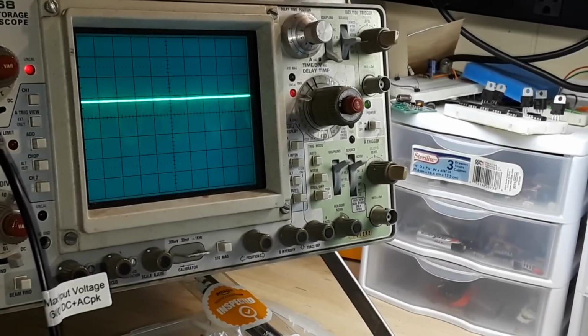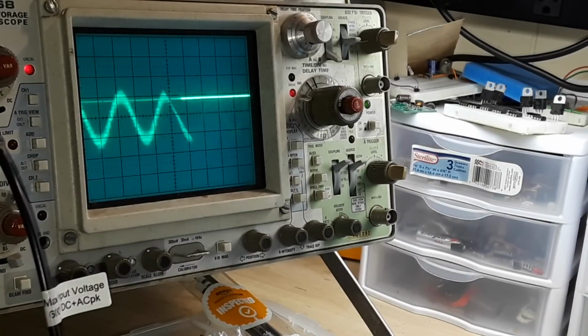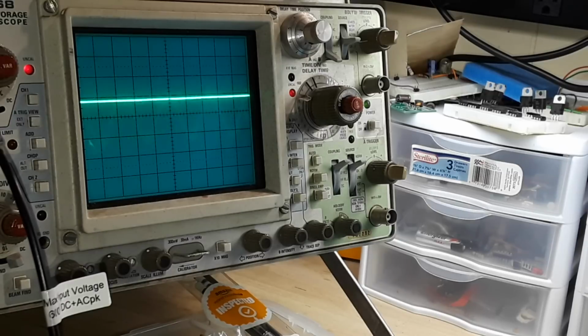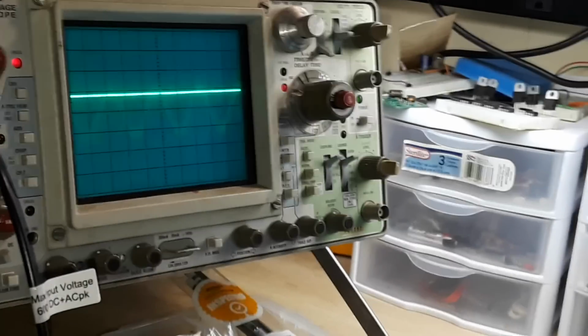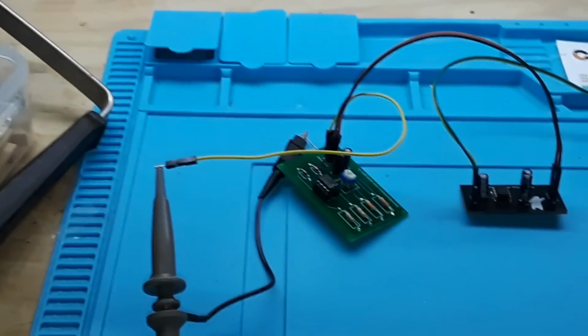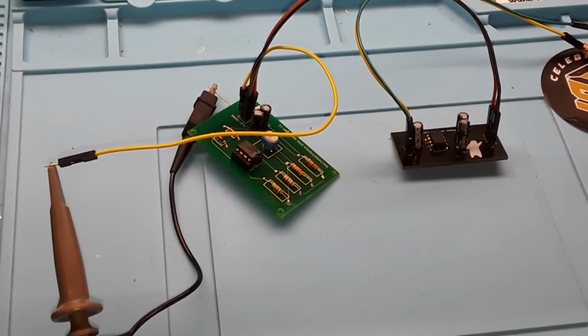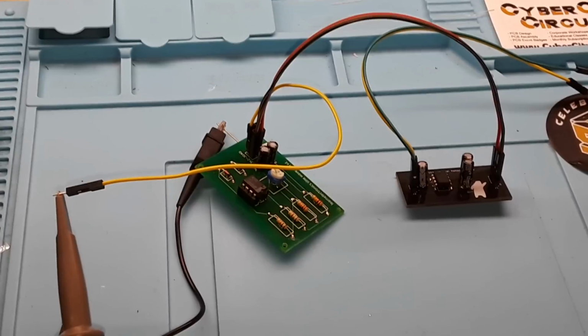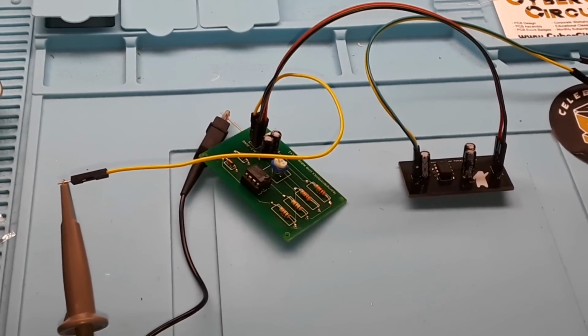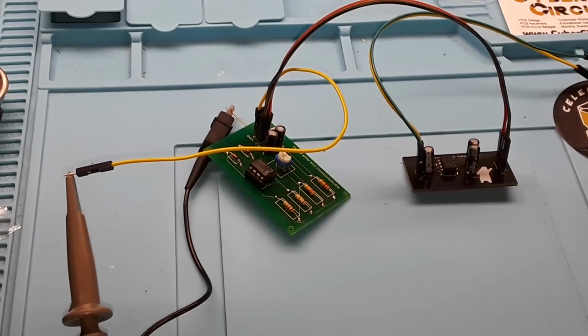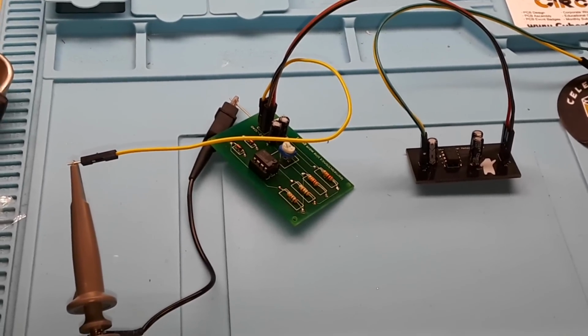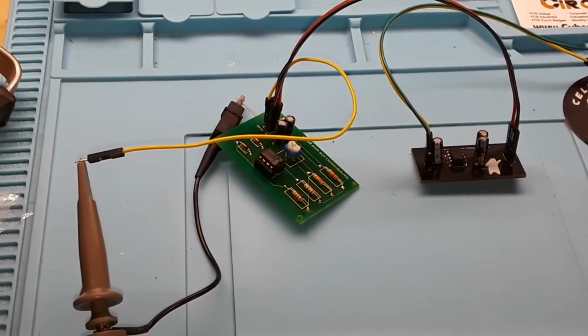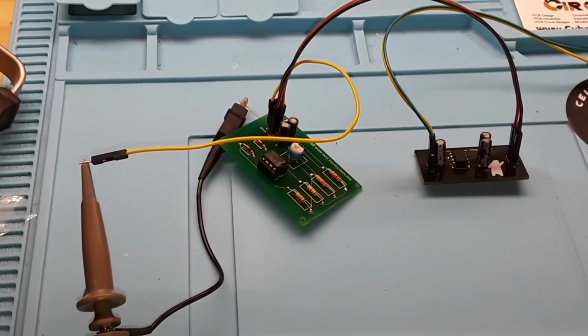I'm getting 308.5 hertz. We figured from the simulation 330, but you know, there you go with your tolerances and everything. Nothing is ever exact. You know what they say? If you can't make it exact, at least make it adjustable. So there she is, a simple sine wave generator, purely for demonstration purposes. A Wien bridge oscillator.